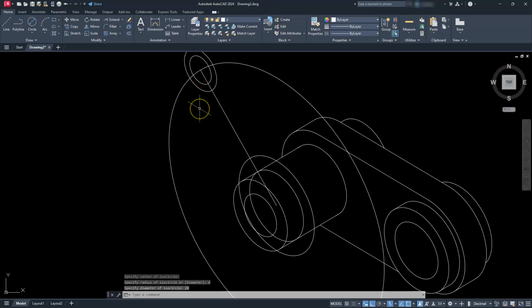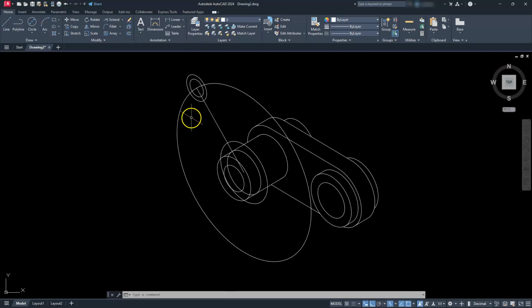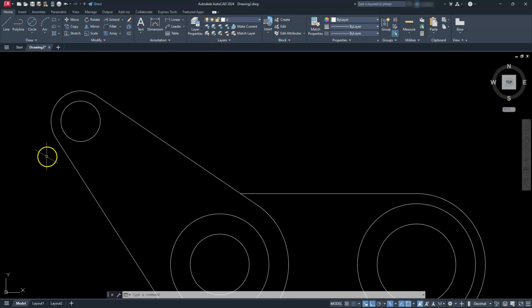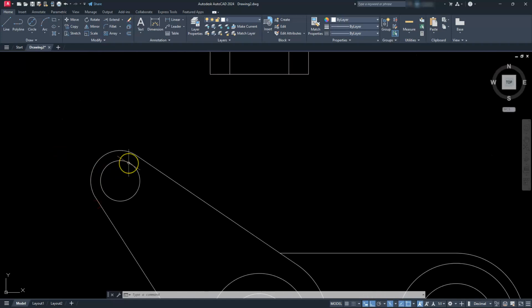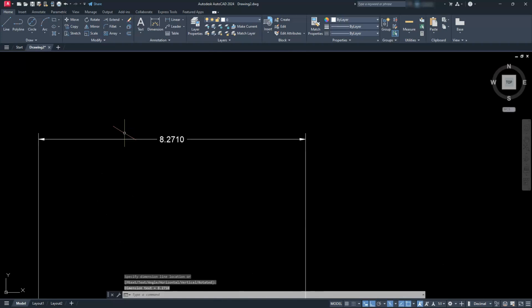Okay. Now this is back again to where we have this tricky thing that is going on, right? How do we figure out where these tangent points are? Well, we're going to have to refer back to the drawing here, right? This time it's going to have two different points. So I'll use the linear command here. I'm going to go from that center to this intersection. And hopefully it's a nice round number for us. And if it's not, as long as we get close enough.